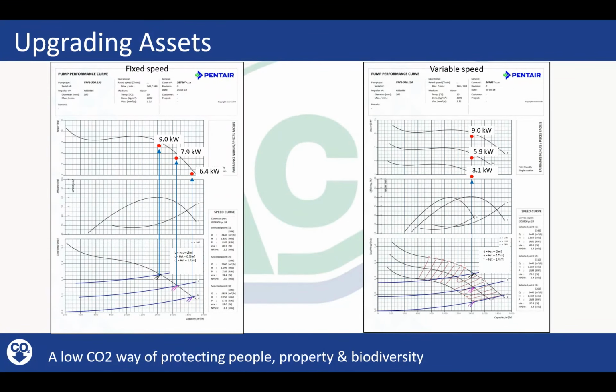You can see here, we're looking at trying to keep the pump, like Appledore, at a steady flow. So as the water level decreases, the head difference, the pump actually slows down. And that's why we've got these three lines. Each line represents a speed. So the top is the fastest speed, middle speed, and lowest speed. Now, that doesn't mean the pump can only operate at three speeds. It's fluid between these three. It's just to show on a chart, we pick particular points, which are a representation of different speeds.